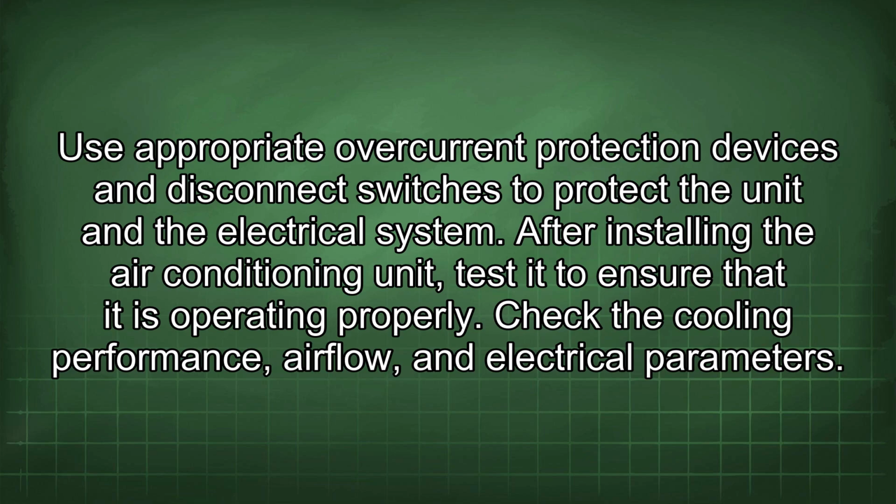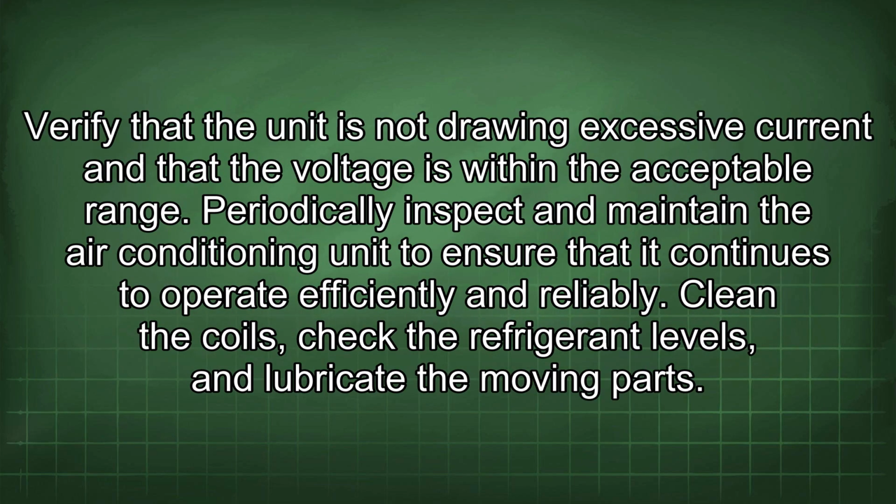After installing the air conditioning unit, test it to ensure that it is operating properly. Check the cooling performance, airflow, and electrical parameters. Verify that the unit is not drawing excessive current and that the voltage is within the acceptable range.